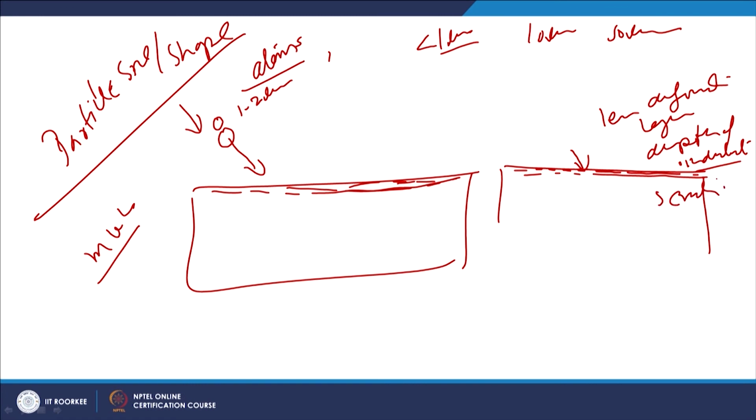So, when the particle size is very small, due to the limited kinetic energy, the surface layers affected by the impingement or impact are very few, and therefore removal of the material from the functional surface is also very limited. So, this is what we can see when the particle size is very small, the removal of material by erosion is less.